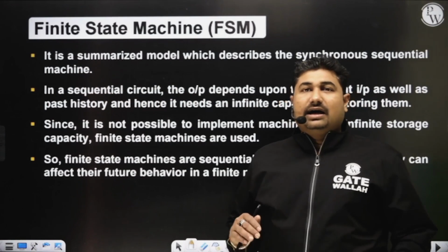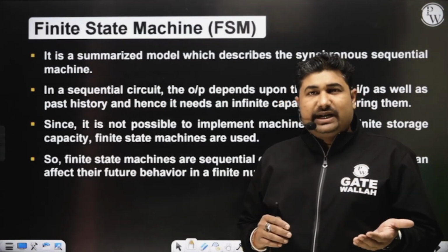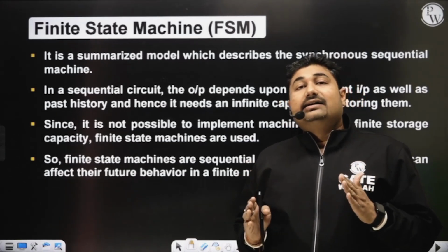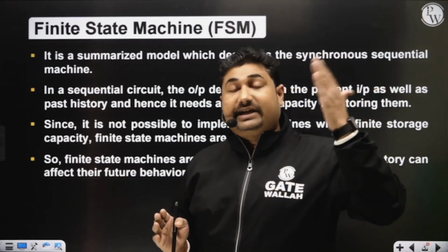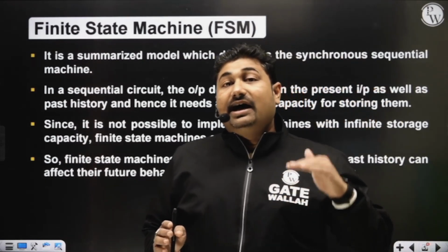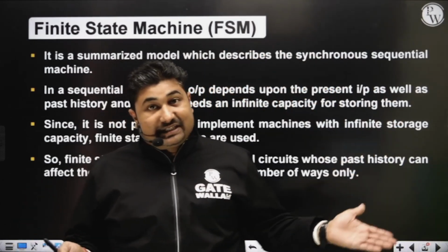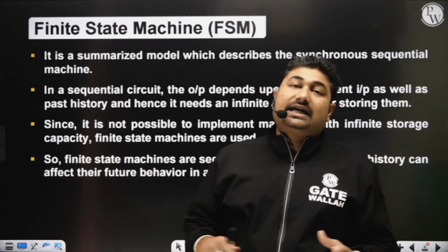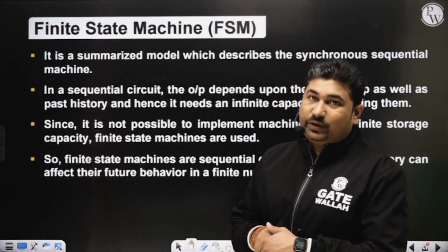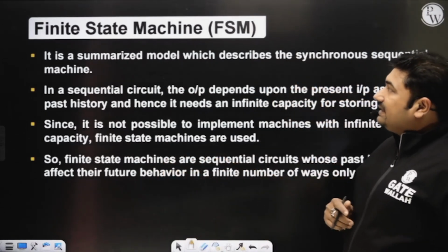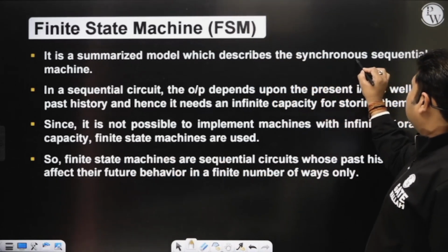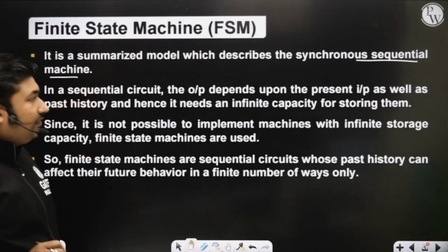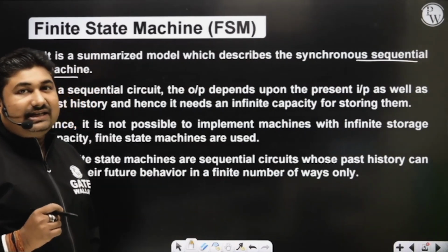Let us suppose the output depends upon the previous state. Then in general, one can think that there will be infinite possibilities of the input state. So we would need a register having infinite capacity to store, but it is not physically possible. So whatever sequential circuit we design is always finite only. Now please observe. It is a summarized model which describes the synchronous sequential circuits.